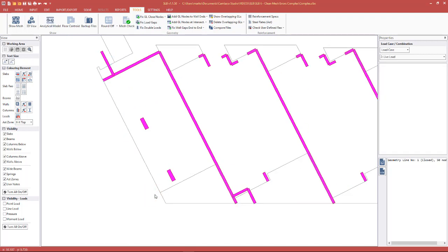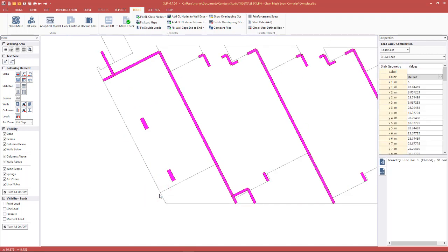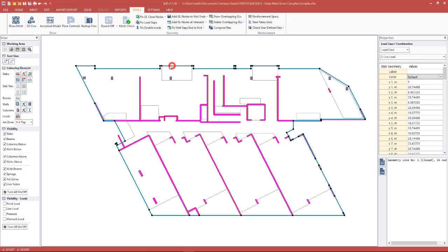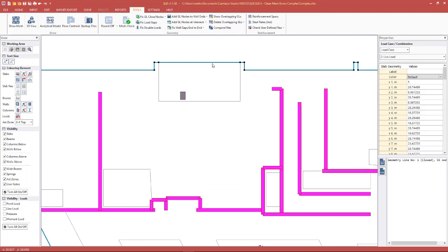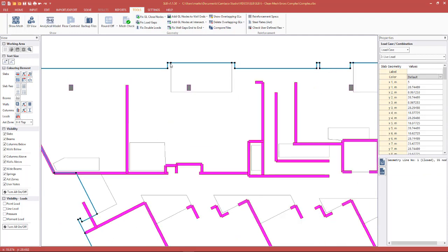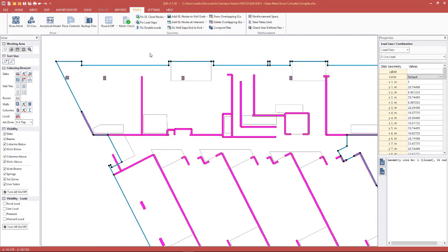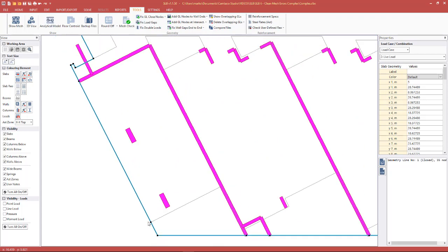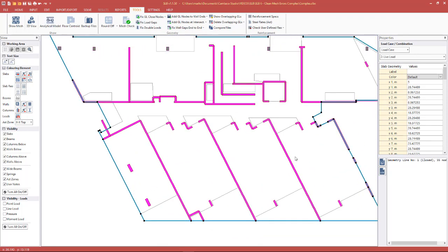So we'll undo that and undo again to get rid of the node, and this time we'll use the tool. So add geometry line nodes at intersect on the current level, and 26 additional nodes have been added. So there'll probably be a few here that were added that weren't there previously. Again, not necessary in the orthogonal direction, but they've been thrown in there anyway. And this particular node was added automatically, similarly to how we did it manually just a moment ago.